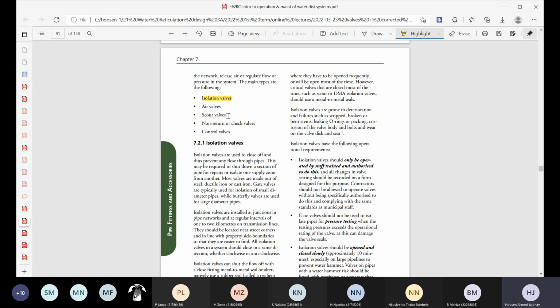So, how would that sand come in? Usually, when you have a burst or cracked pipeline, sand or whatever may come in. They may replace a section of the pipeline, and dirt and grit may come into the pipeline. So after that repair, they would scour the pipeline. They just waste a certain volume of water, so that the water that remains in the pipeline is potable drinking water, clean and free of contaminants.